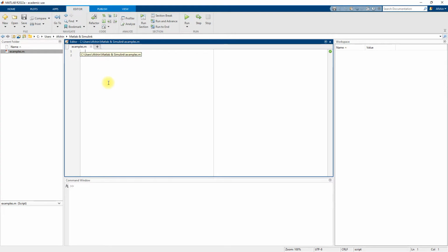For this one, we had a transfer function that had the numerator as 0.8. So I'm going to define numg for the numerator as 0.8. I'm going to define deng as the denominator coefficients in the same order as they appear in the denominator. So we had s squared, its coefficient was 1. We had 3s, its coefficient was 3. And we had 12, a constant, so we put 12. So we have our numerator and denominator coefficients.